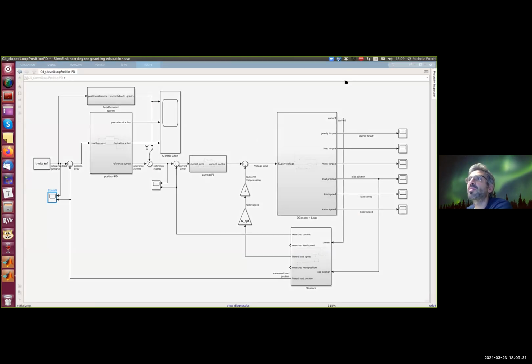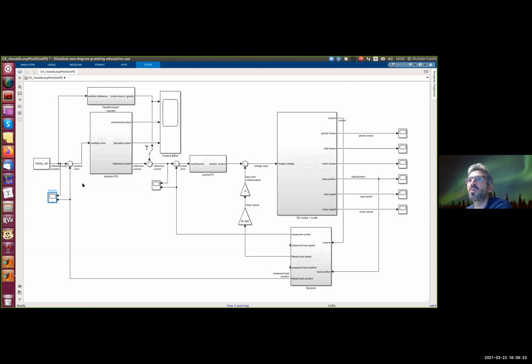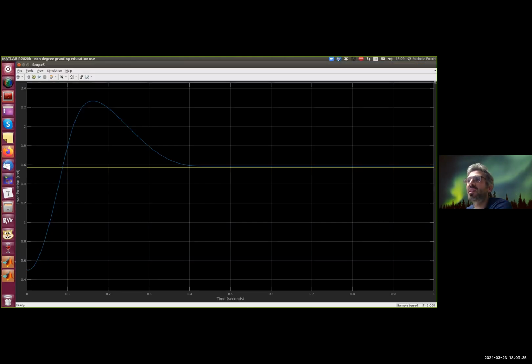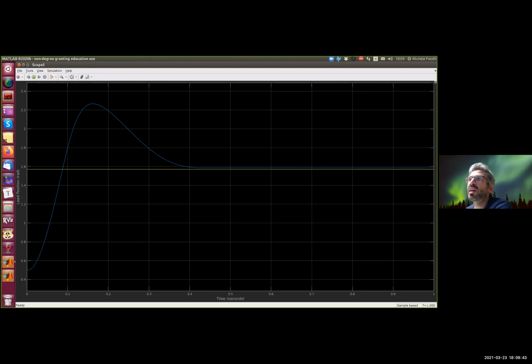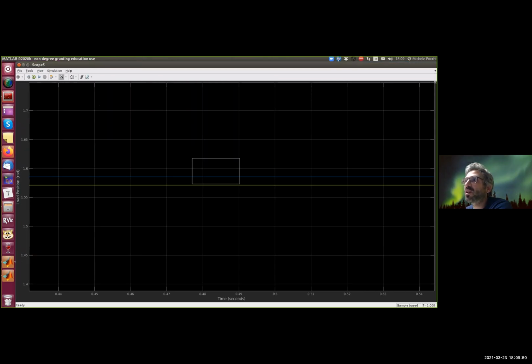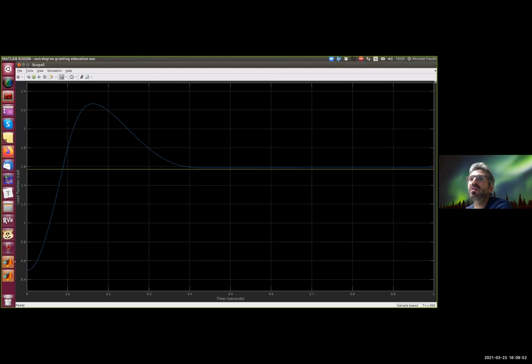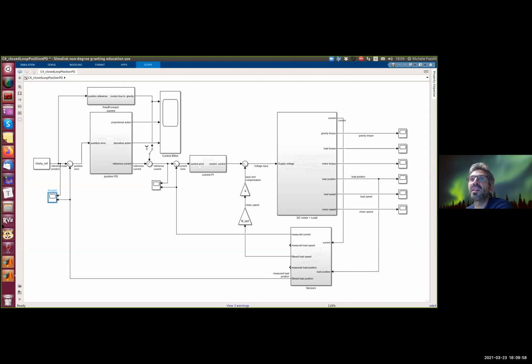To play around, because you remember in the lecture where we said what happens playing with the different gains, the proportional derivative one, we have different responses. So we said that increasing the proportional gain doesn't nullify the steady state error, but reduces it. And actually it's true, the steady state error was reduced. But on the other hand, it is increasing the overshoot and going toward instability. How can we say that?